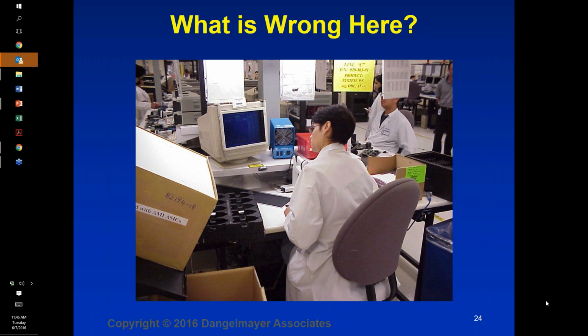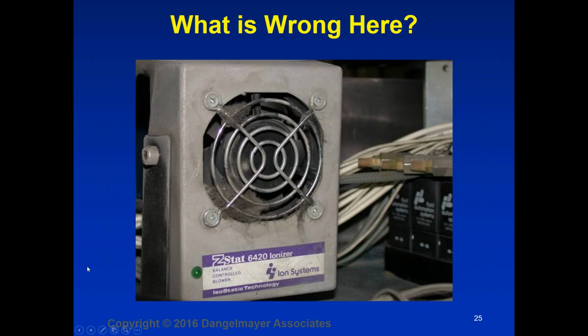The ionizer tends to be turned towards the person rather than towards the work. If you had markings on this work surface of where the ionizer should be, you'd be able to tell right away that it was not in the right position. The products are there down on that carrier on the left, but this ionizer is definitely directed at the person as a cooling device. Next slide.